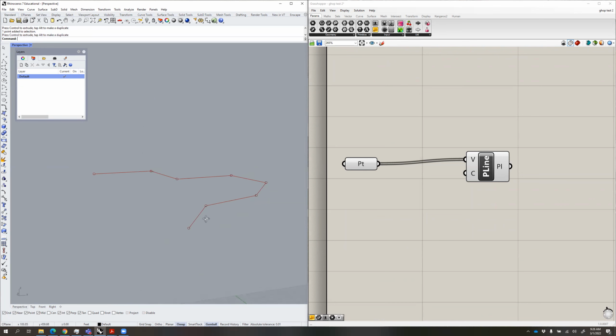So the first thing we're going to do is that, typically, with landscape architecture projects and paths, we like to have the turns of the path be a little bit more gentle and not so angular and sharp and aggressive. It just feels more natural to the human experience to have curves in the sides of this. So we're going to use a fillet component on this polyline to add that nice curvilinear geometry.